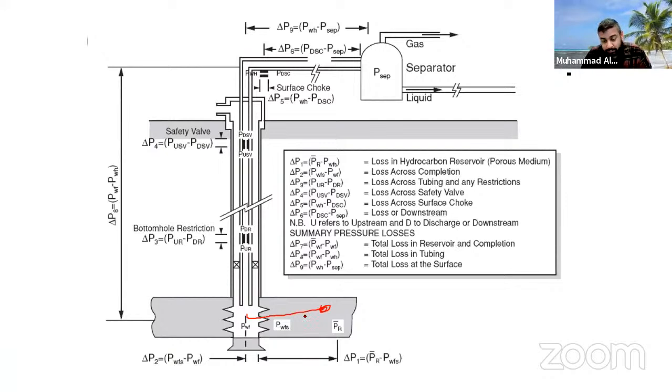As a production engineer, you must imagine that the oil cannot flow from this point to this point unless there is a pressure difference. There is a delta P. Let's say here is 2000, and here maybe is 1000 or 1500. So there's always a change in pressure from this point to this point. Pressure is reducing. That's why the oil is flowing from high pressure to low pressure. So likewise, we have some pressure loss. And why is this pressure loss happening here? The pressure losses are happening because of the restrictions, the perforation restriction, because they are very restricted here.